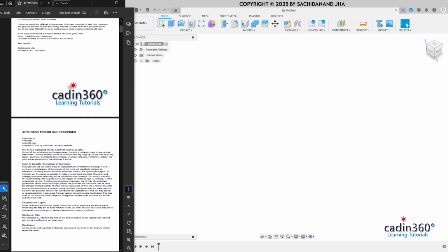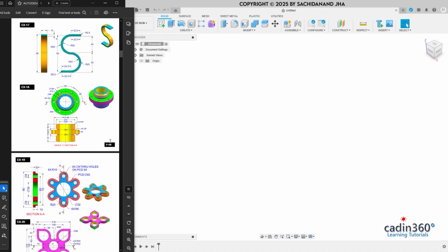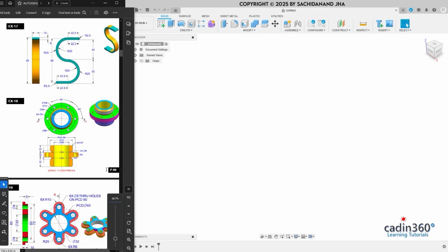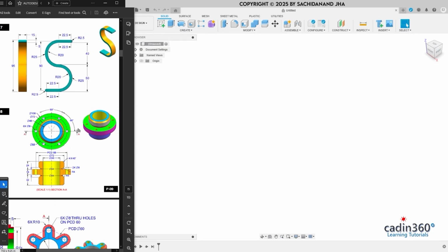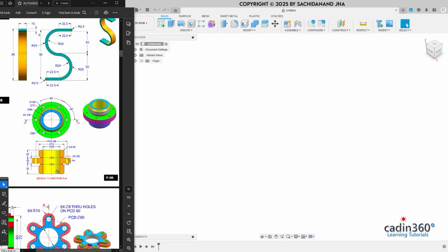Today in this video we are going to complete exercise 18. Okay, so today we are going to create this 3D model using these dimensions in Fusion 360. So let's start. In this modeling exercise, first we will create the half section of the 3D model, then we will revolve it around the central axis, and then we will create these holes by creating a circle. Then we will circular pattern it and then extrude it to cut it from the main body.